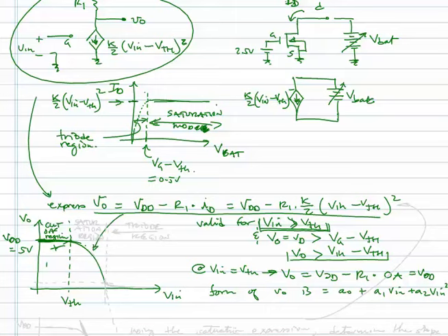But then at some voltage here, Vd is going to fall below the gate voltage minus the threshold voltage, and it will no longer be in the saturation region. We're not going to try to model that now, but I'll just show it as this thing not continuing to go negative like this. It'll curve out, take a swing, and asymptotically go to 0. And this middle region is the saturation region.